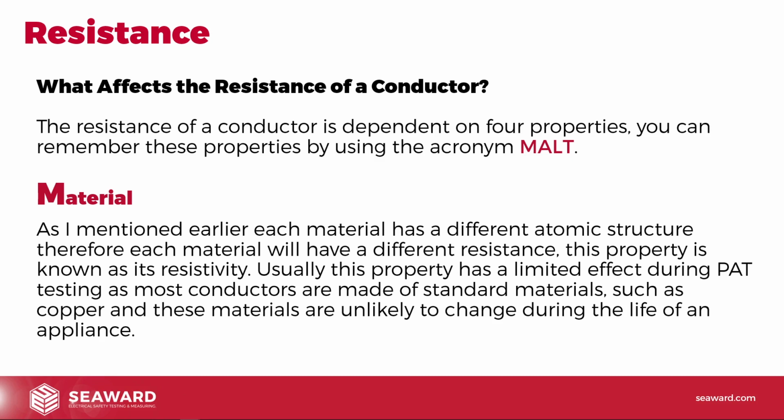So when you're PAT testing from one year to the next, you're not going to see any changes due to the change of material, because a copper cable is not going to turn into gold. Wish it did, but not going to happen. So the material, although material is part of MALT and affects the actual properties of a conductor, it's very much fixed. We pick copper for a reason, because it's a very good conductor, and that's it. It's not going to change. So from a PAT point of view, yes, it's good to know what that material is.